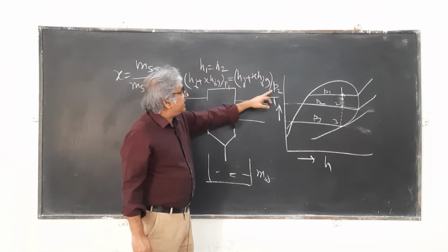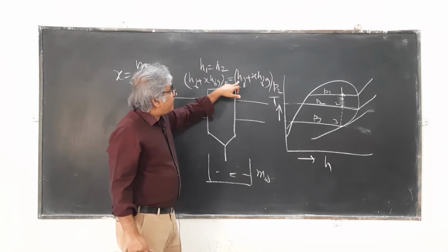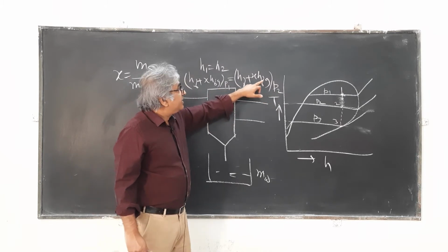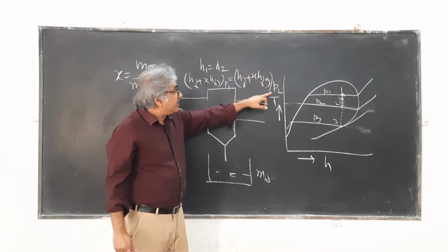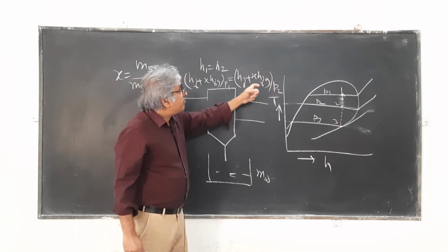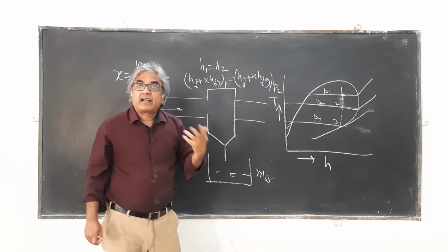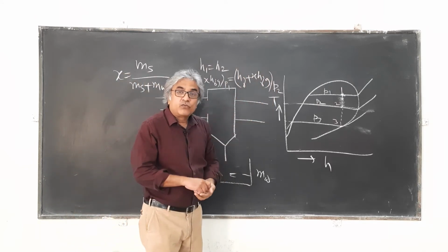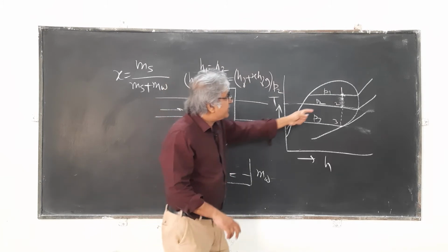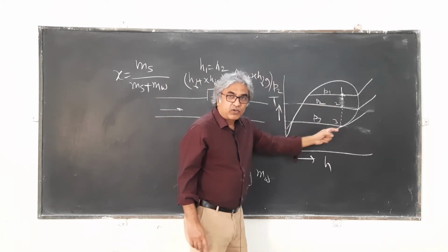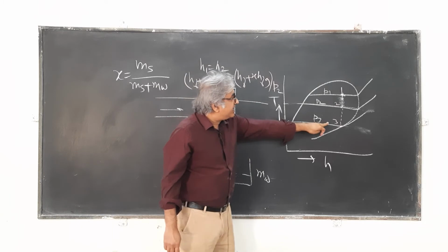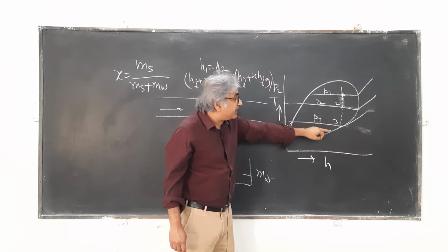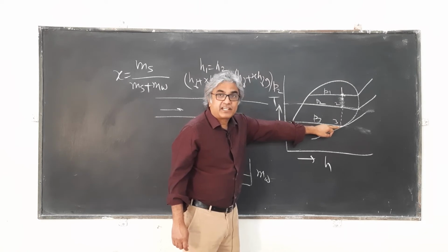But on the right-hand side, you know the pressure, so you can find HF corresponding to this pressure from the steam table. You can find the value of HFG, again corresponding to pressure P2, but there is one more X that is unknown, right? So you want to get rid of this X. What does it mean? It means you need to expand the steam further. If you expand it to P3, let's say the steam becomes dry saturated.